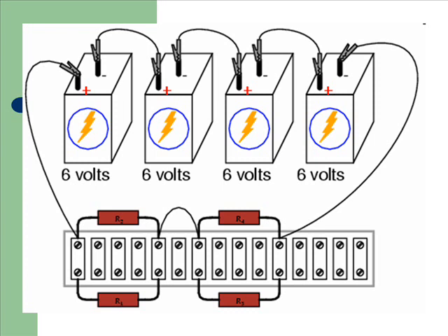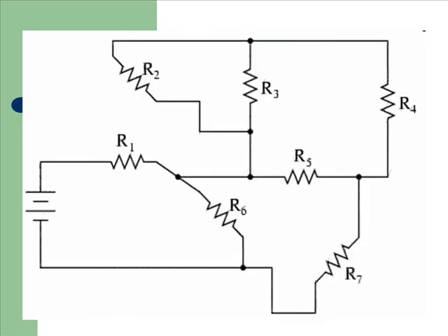Another terminal strip layout, simpler to understand and relate to the schematic, involves anchoring parallel resistors to the same 2 terminal points on the strip like this. Building more complex circuits on a terminal strip involves the same spatial reasoning skills, but of course requires greater care and planning.